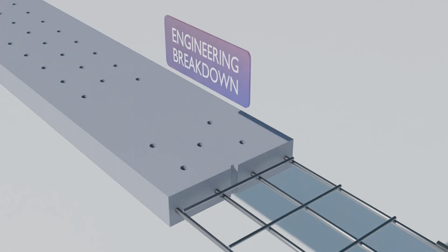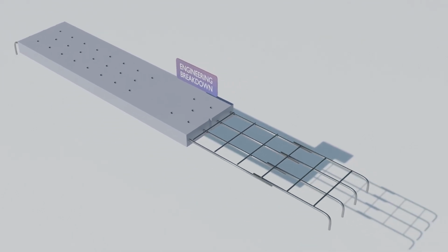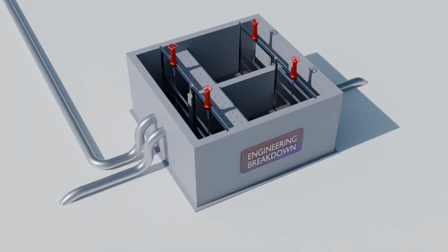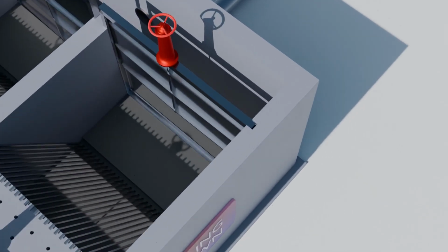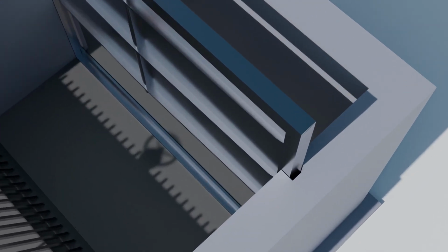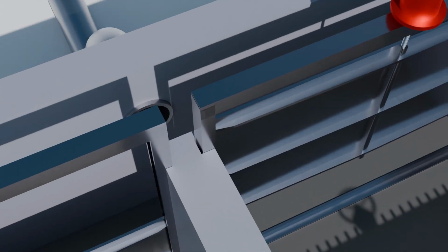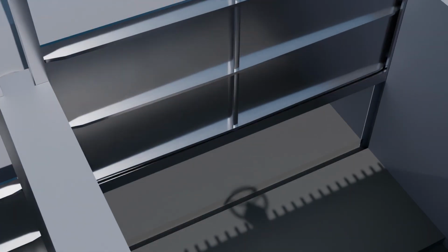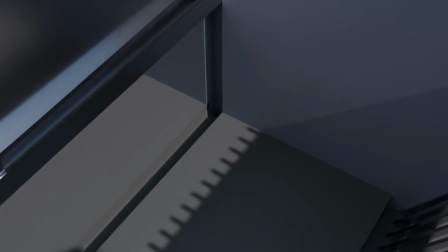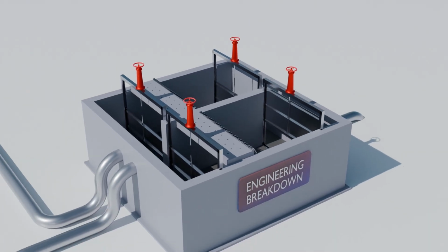Let's finally look at the embedment indentations in our structure. The concrete and walls have indentations where steel gate slots are embedded. Our gate then slides in these steel-embedded slots. It should be leak-proof and well embedded. The PCC cast on the base of the slab also has an indentation for the gate slot to fit as shown. The screens also rest in another cavity provided at the base of the structure as shown. This completes all the relevant details regarding a screening chamber.